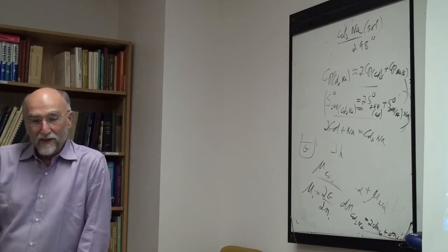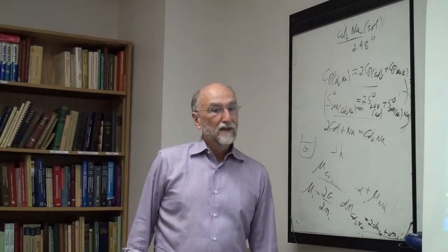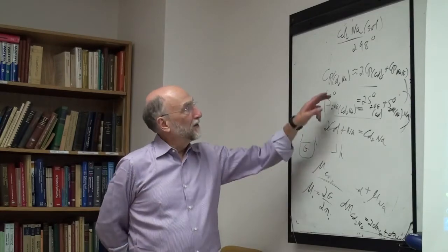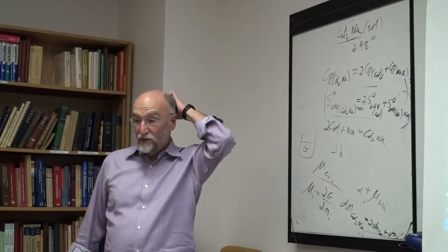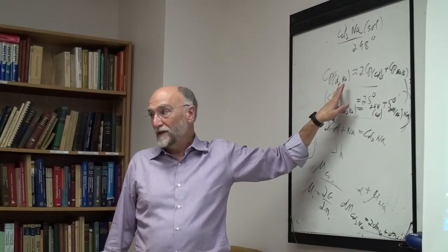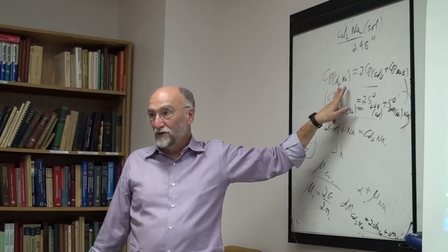Okay, so you've got to think of, even 10 joules per mole Kelvin is a typical entropy of melting. Now, think of entropy as the disorder. If you're mixing two solids to get another solid, you don't expect the entropy change to be greater than the entropy of fusion unless you've got a really, really ordered solid.